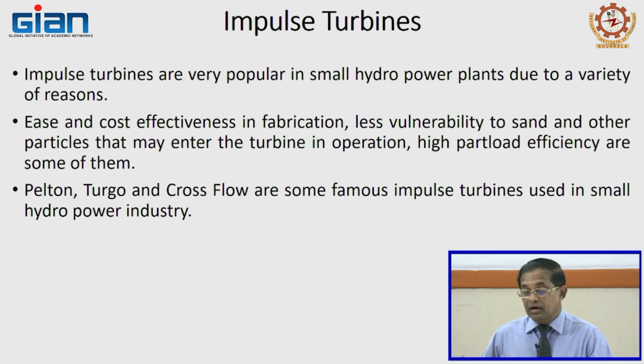Normally in any country or any region, when they start the implementation of small hydropower projects, they start with high head project opportunities, because they are more cost effective, easier to construct, and smaller in size, because the amount of water you have to handle is smaller: Q is small, H is large. High head projects are easier to implement.